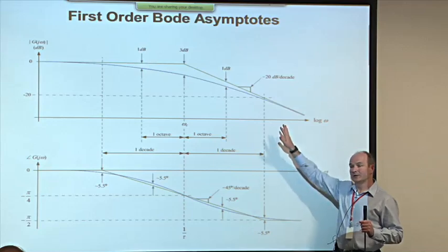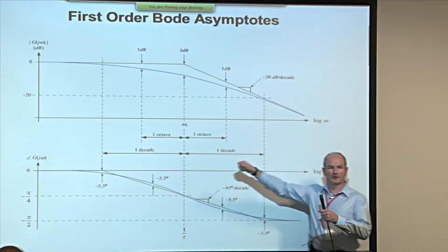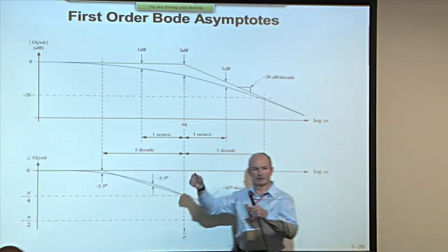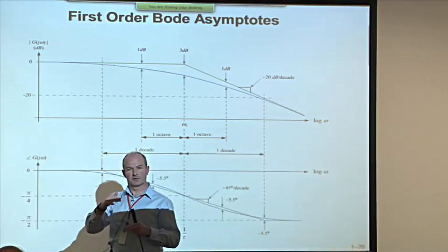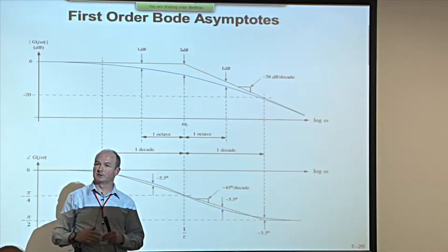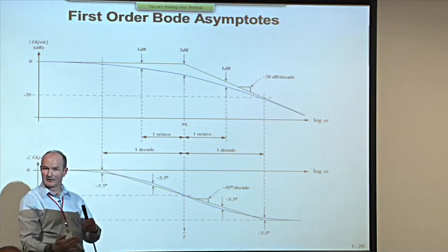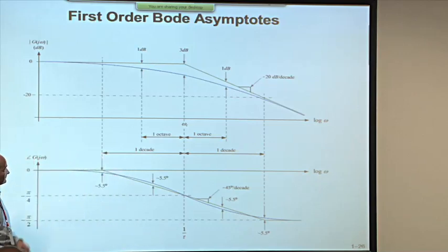But actually, when you look back at the graph paper, when people used to plot these things by hand, you had log linear graph paper and you would plot them. The graph paper was always scaled so that the slope was exactly that. A minus 20 dB per decade slope was exactly minus 1. It was 45 degrees going down. So they're still called minus 1.